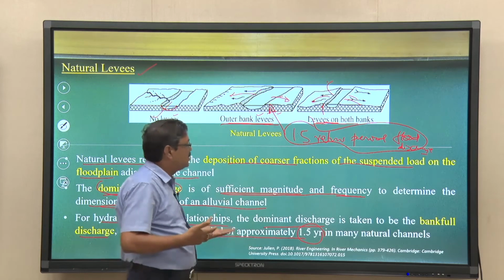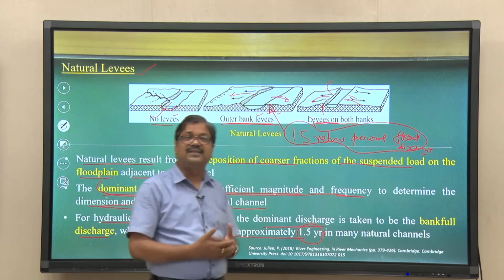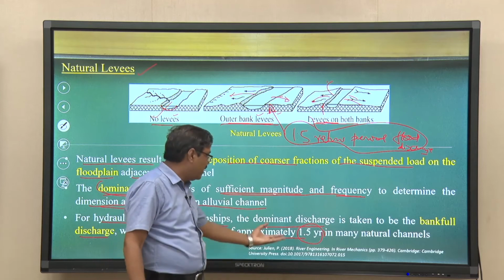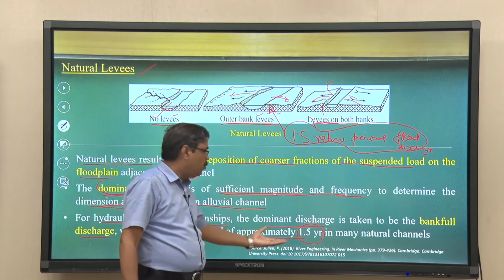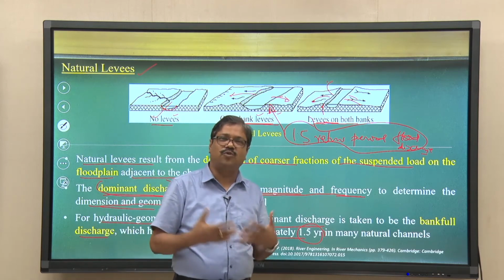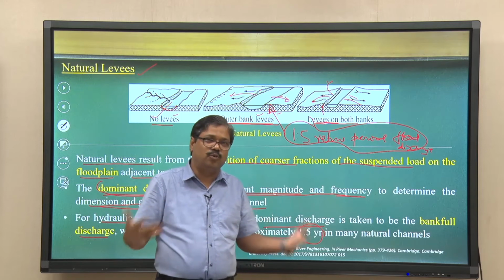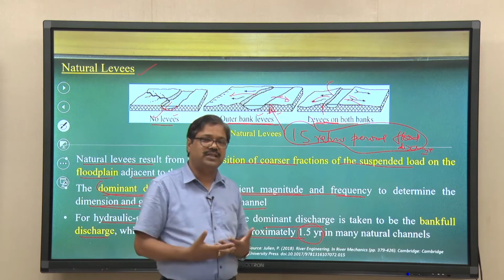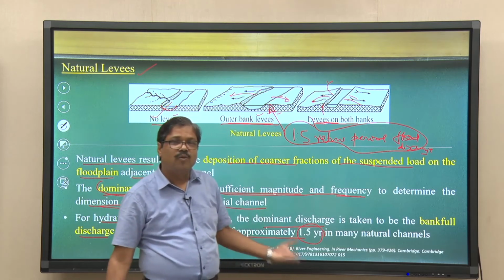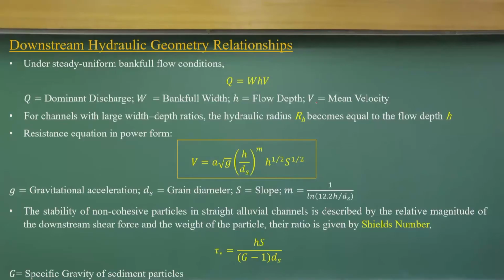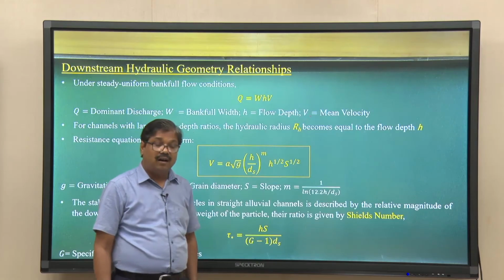So, this concept can help us understand how things are happening at river scales, and that is the regionalization idea, that it has a return period of 1.5 years. But no doubt we should do regional studies to find out whether it is 1.5 years or 2 years for the Brahmaputra river, the Ganges or the peninsular rivers. Those research studies need to be done to see whether a 1.5 year return period is okay for us.